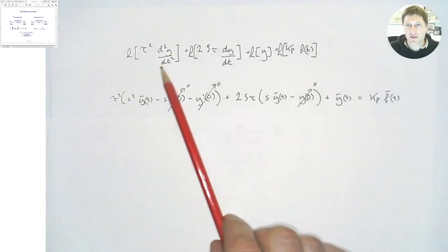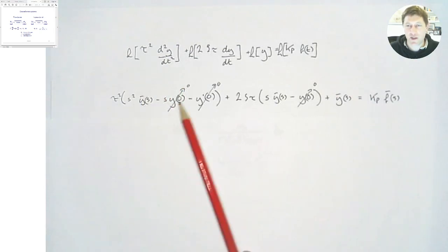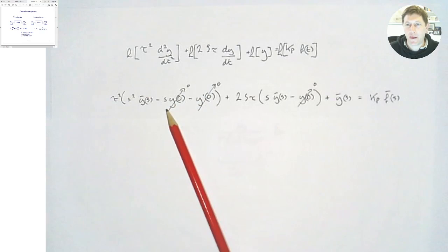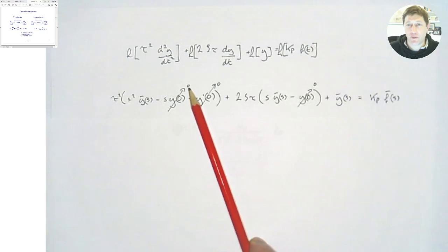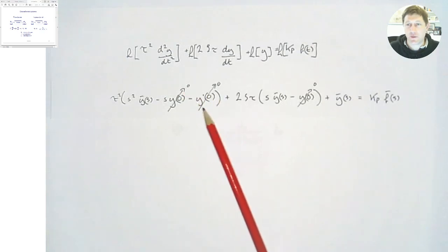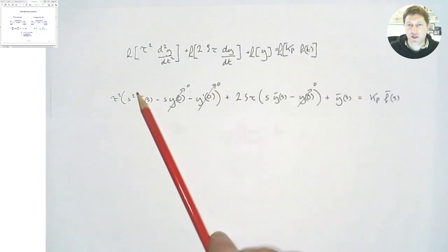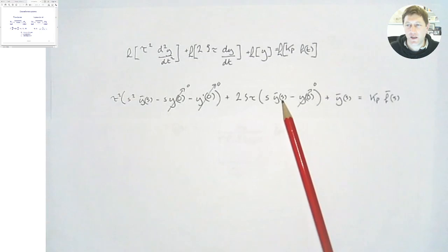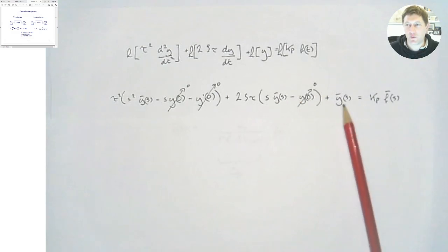So to find the second order differential, you have s squared times the Laplace transform of y minus s times the initial value minus the gradient at time 0. Well, we're looking at the deviation from steady state, so at time 0 there is no deviation because it's at steady state, so that's 0. And at time 0 it's at steady state, so the derivative of y is going to be 0 as well. That's a nice simplification again, so we just have this term here. Likewise, when we take the first order derivative, it's s times the Laplace transform of y, and the initial value is 0 again. Laplace transform of y and Laplace transform of f. And so that works out nicely.